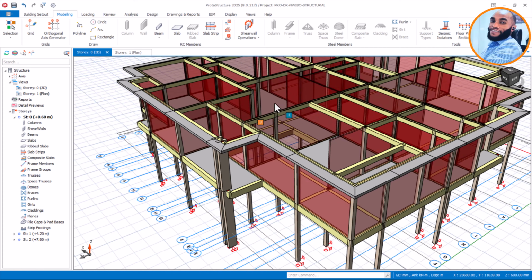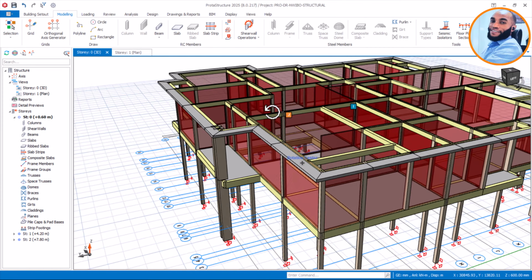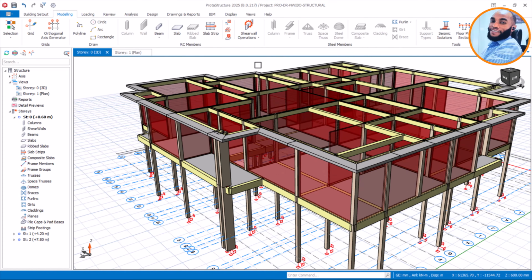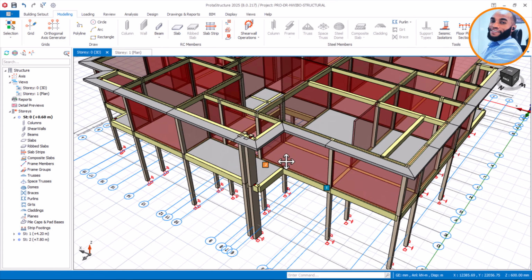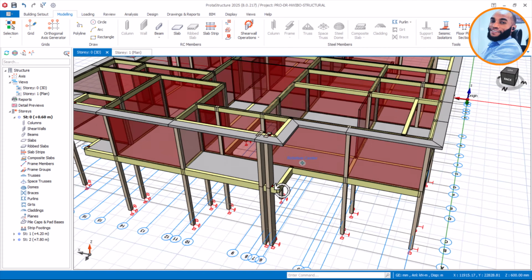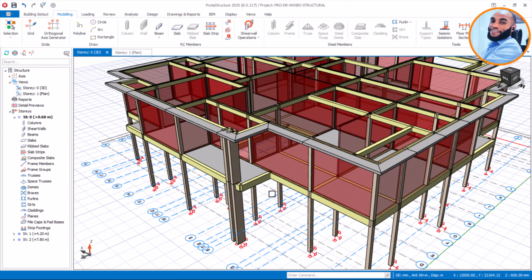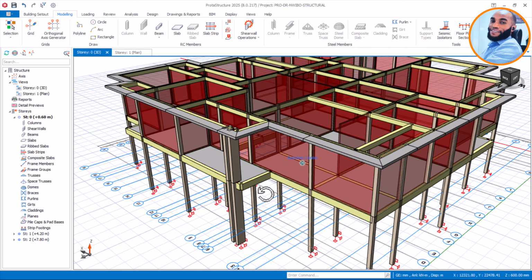In this case, this is just a one-story building, so we're using a strip foundation. The major factor is the bearing capacity of the soil. From the soil report, the soil bearing capacity is a bit lower than the standard for choosing a pad foundation.